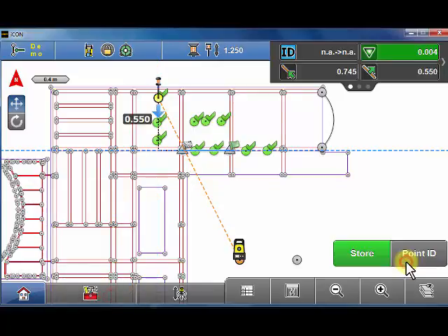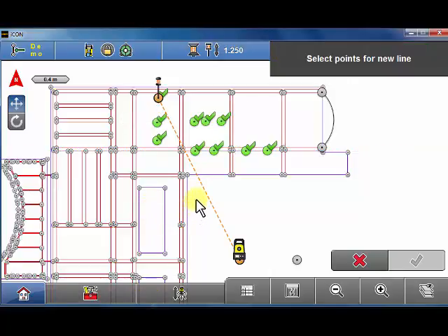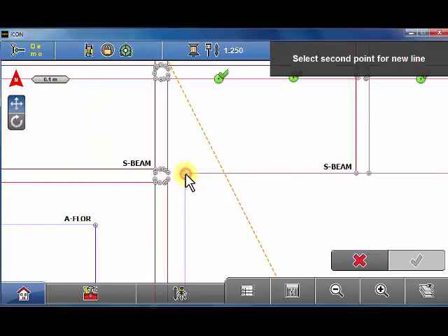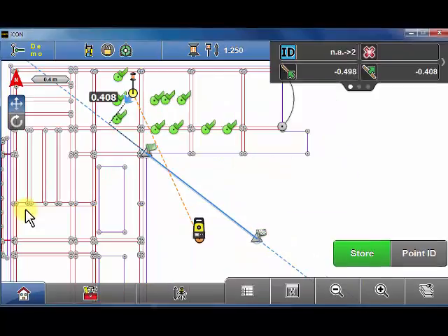If we're in the situation that we have to lay out an excavation trench between a manhole and the building, but the line cannot be selected, we can create it by using Connect Points. To connect 2 points, we just have to select them on the map. It doesn't matter which point you select first. The starting point of a reference line can always be changed using the Flip tool.